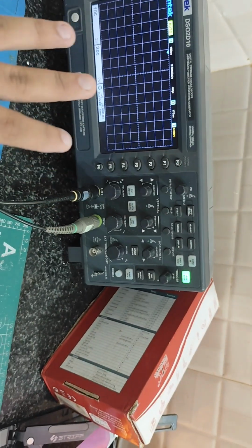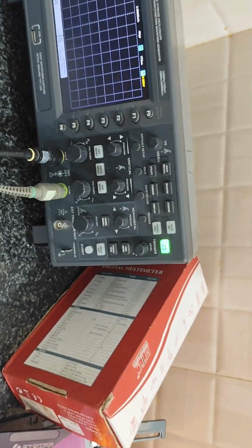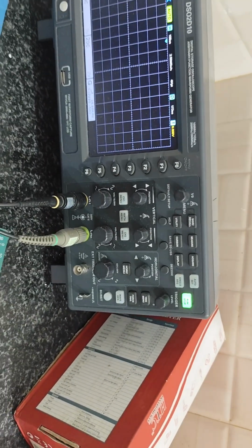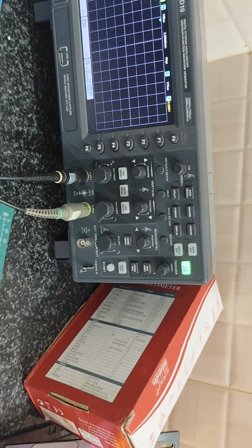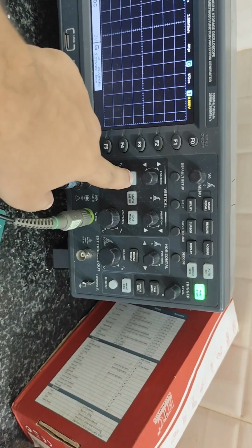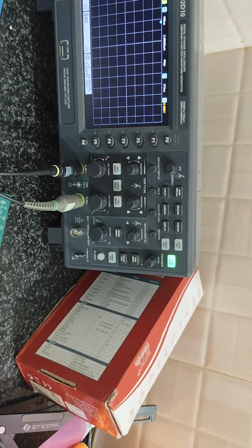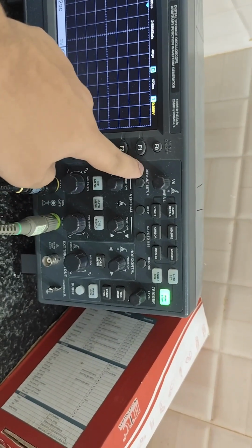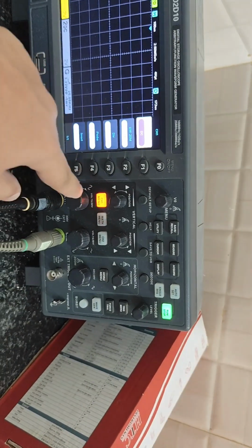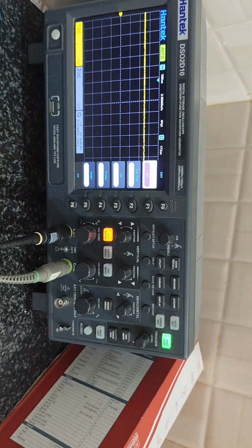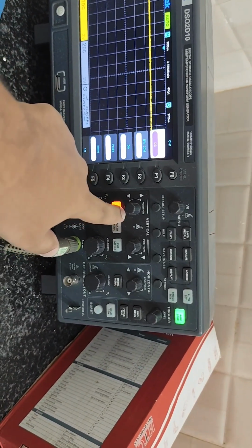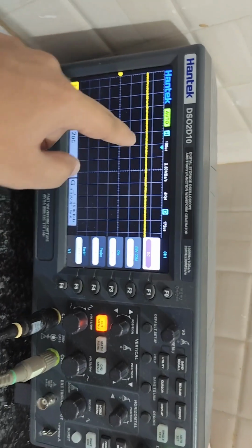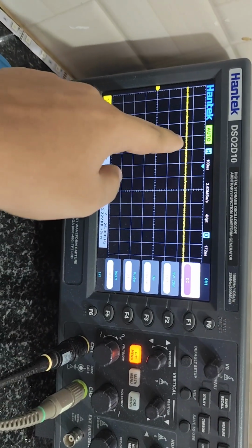Each oscilloscope might have some different settings, so you might need to tweak and research a bit about it, but mostly the functions and names would be similar. Generally it's a separate dedicated button on a scope, named as some coupling type or something, but for this scope we have it in the settings menu. Once we turn on the channel option, you can see there's a line at approximately 2.5 divisions from the midline.